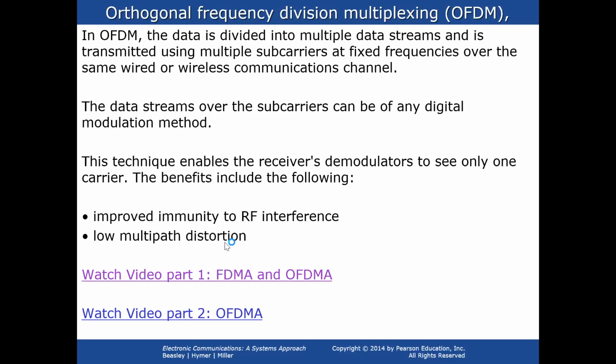Delay spread. As a consequence of multipath propagation, the duration of a symbol gets extended. This may interfere with the next symbol. This is called inter-symbol interference or crosstalk. Guard periods are introduced to avoid crosstalk. Frequency selective fading. Signals having bandwidth higher than the coherence bandwidth of the channel face variable attenuation at different frequencies. This ultimately distorts the signal, giving rise to frequency selective fading. Complex channel equalization techniques are employed to reduce it.